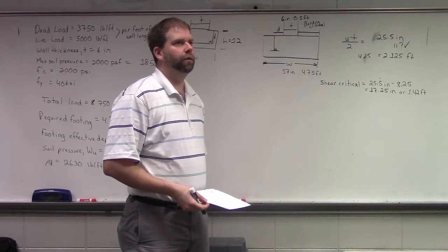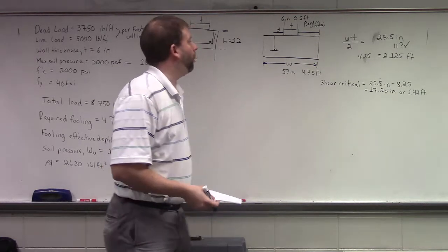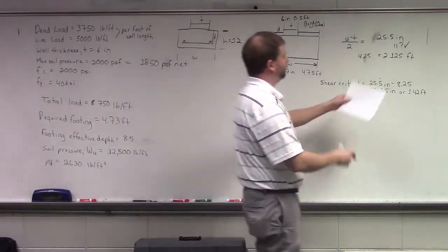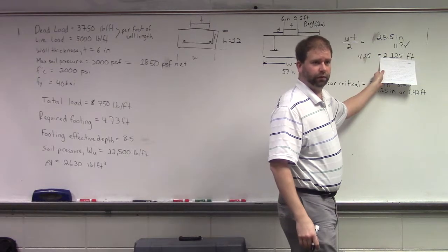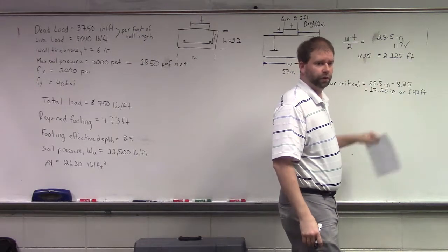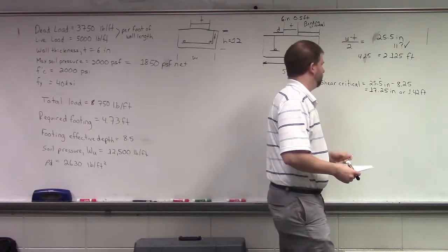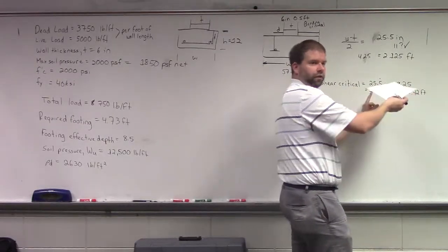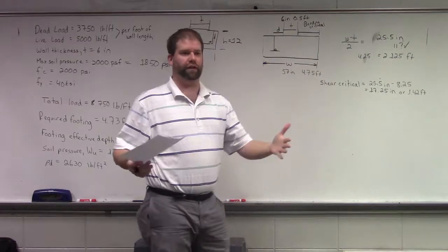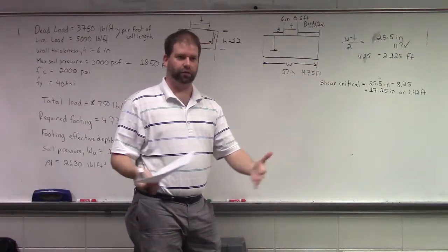No, you do 2.125 minus 0.71. We switched ours over to distance. That's 2 feet. Subtract it from, you want to set it up like this, you don't want to run it the other way. Because you're never truly going to have a negative dimension in the field.